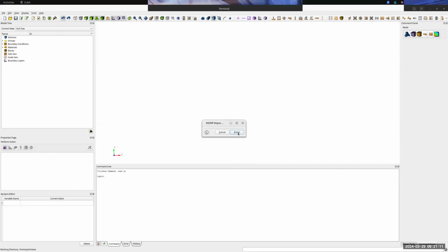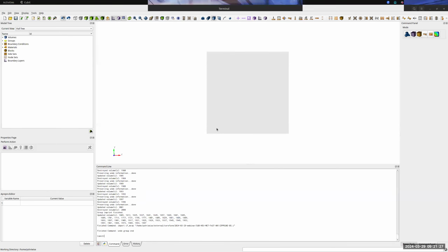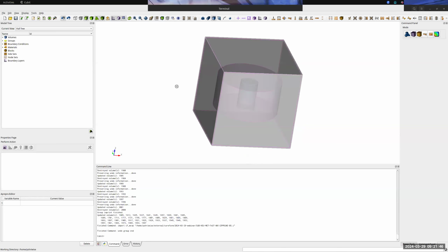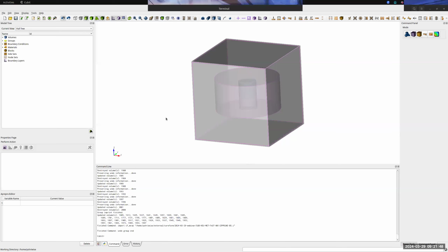And if I go ahead and open this and click on finish, this is a place where we may be adding some import options in the future. But for now, we just are going to use all the default settings of this underlying tool for importing MCNP models. It's going to go through this whole process, and it's going to interpret all of these different Boolean combinations of the CSG primitives like cylinders, spheres, planes, etc., to produce this CAD model that we see here of the zero power physics reactor.